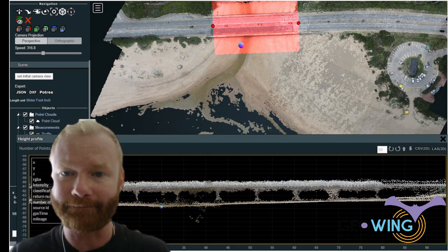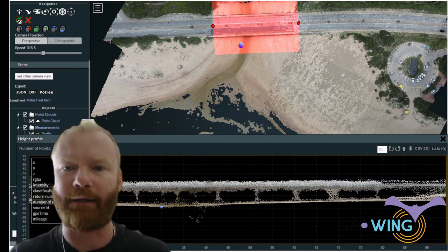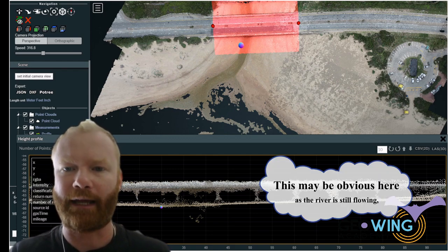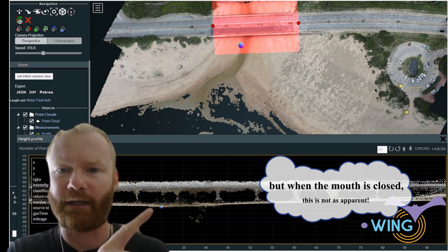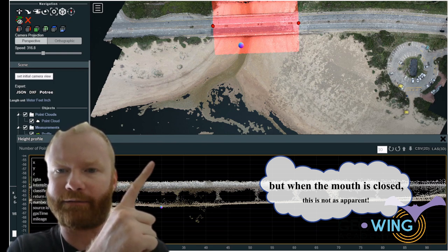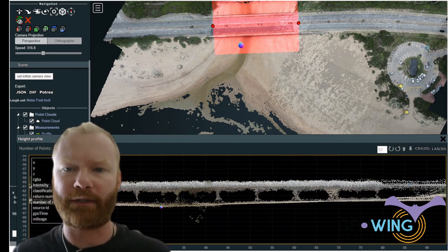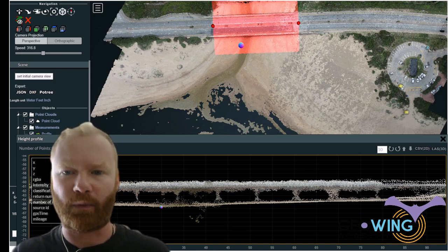So how is this useful? Well, we can have a look at the profile of the river system and find its lowest point. That is represented here by this dot, which is also represented in the 2 dimensions by the dot above. By knowing the lowest point of the river, we can therefore determine where we need to dig the slit trenches. So when the river does start to flood, the water will break through at the optimal point, preventing flooding to the surrounding infrastructure and recreational areas.